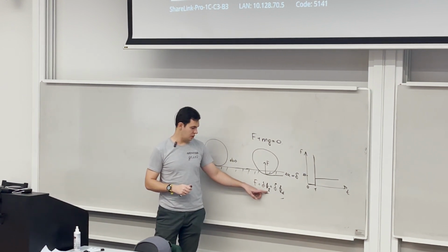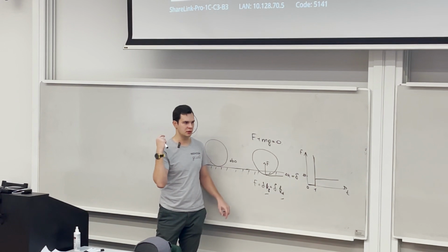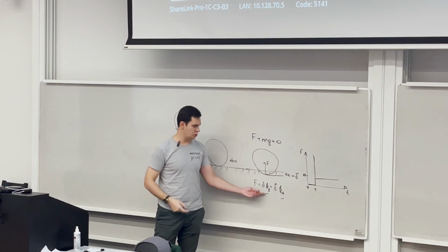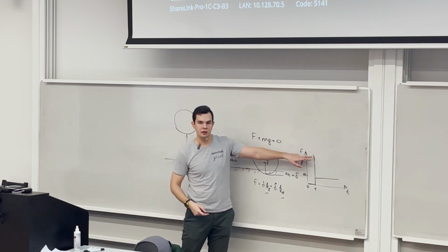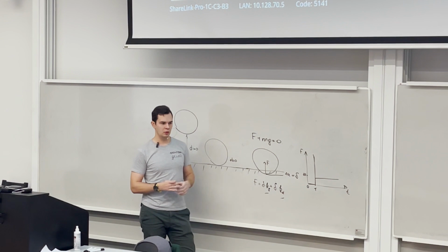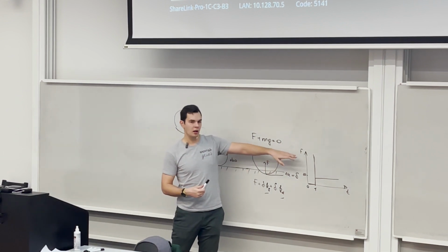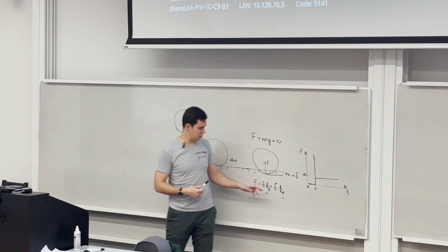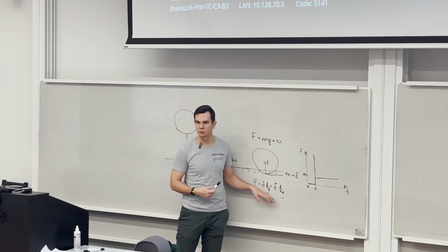If you want it to be almost 0, to asymptotically tend to 0, you need to choose very high coefficients, but it will lead you to very high forces. If you want to consider that your bodies are elastic, they can deform, and you want to get lesser values for forces, you need to use lesser coefficients. So it's something that you need to tune on your own.